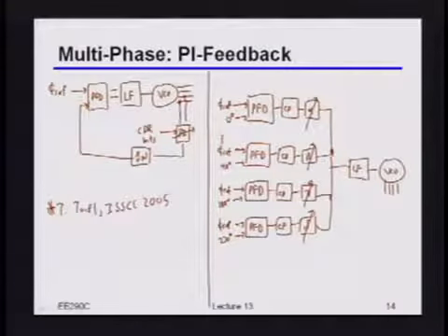So can't you like program the dividers rather than putting an extra coefficient? Program them how? I mean, it's a digital counter, right? So shouldn't that be easier to program? I'm not sure whether it'll work, but having like different counts. Well, okay, so I believe what you're saying is similar to what Chintan was suggesting earlier, which was, imagine you just had a divider where you changed the feedback clock into that divider. So let's say on one phase you fed it with the 0 degree, and then next time you fed it with 90 degree, and you dithered between them. Is that what you're suggesting?